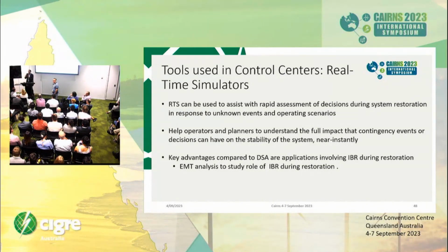If you lose SCADA from a certain region, and if you do not have good bad data detection techniques, your state estimator will start diverging. And suddenly you are sitting there for 15 minutes without any observability of your system. So there are techniques being developed, recursive approaches and resilient state estimation algorithms, which can help you identify that area and isolate it so that you can still get an unbiased solution for the rest of your system.